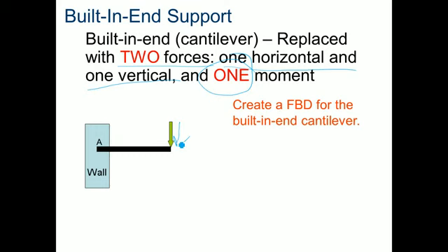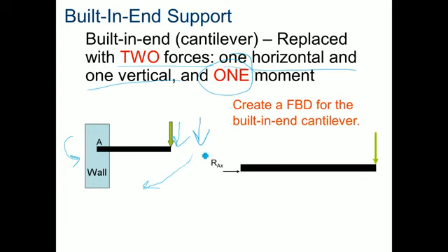So if I look at this specific item, if I have a weight coming down here at the end, the shelf, or whatever it is that we're talking about, is going to want to move in this direction. Well, I have to have a twisting force at the other end moving in the opposite direction, which we will have. First of all, at the end, it's end A, I have two forces: reaction force at point A in the X direction, reaction force at point A in the Y direction, and then here's my moment at A in the counterclockwise direction.